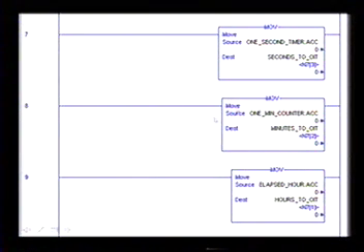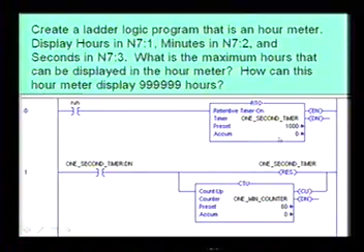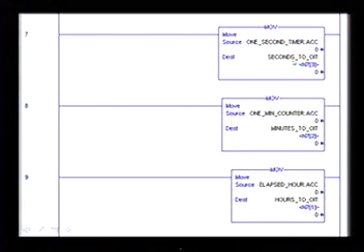And then I moved it over for you. Oh, I did do alias. So 1 second timer dot accumulate. So that was at the top. The accumulated value of the 1 second timer would go in there. So we'll just move it into seconds to OIT. And we did an alias N7 in brackets 3. So it's not :3, it's N7 in brackets 3. And we covered that in detail in course number 2, I believe. Probably even a portion of that as well.